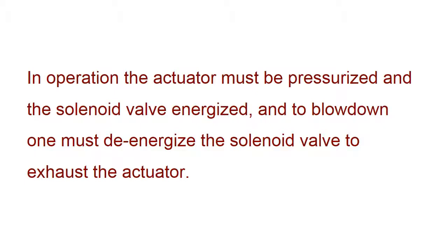In operation, the actuator must be pressurized and the solenoid valve energized, and to blow down one must de-energize the solenoid valve to exhaust the actuator.